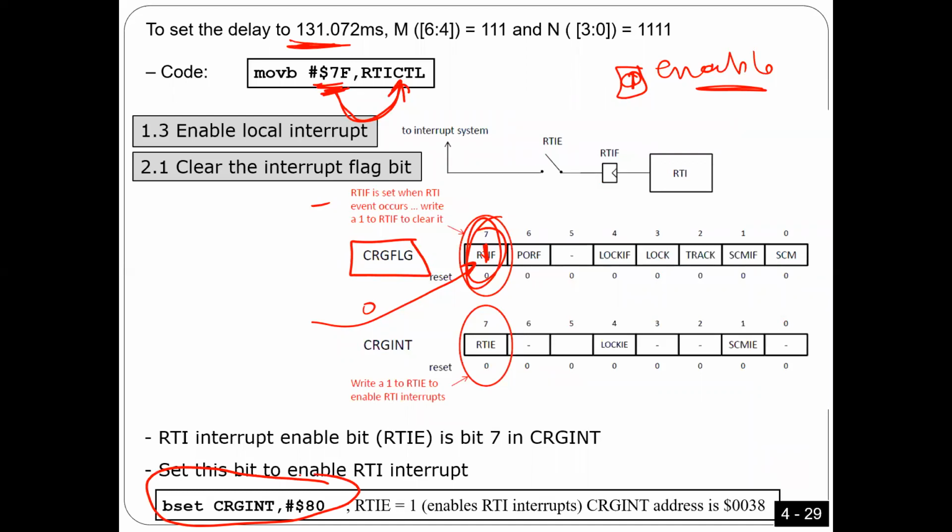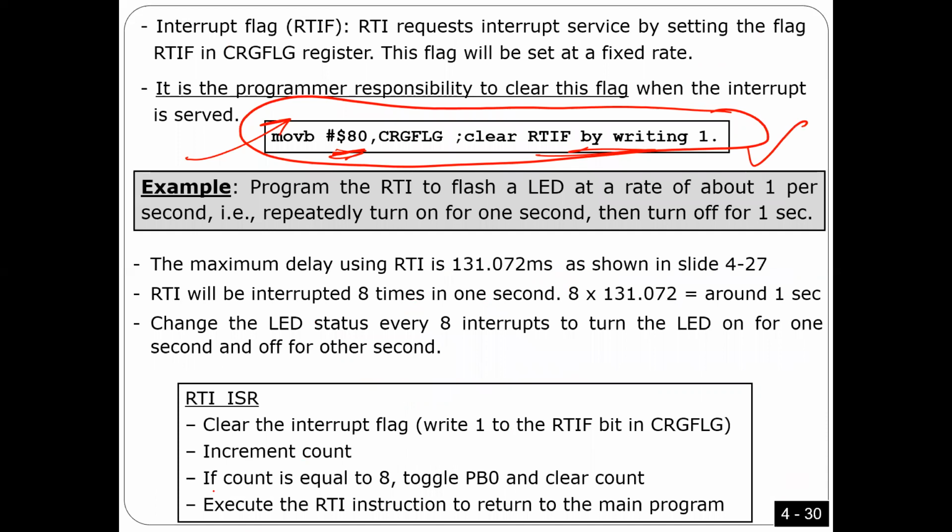If you want to disable interrupt, and that's what you need to do in the coming lab, I guess, you have to use bit clear instead of bit set. This is number 3. Number 4, in the interrupt subroutine, you always have to write this instruction to clear the flag bit. Any question before I choose the program?